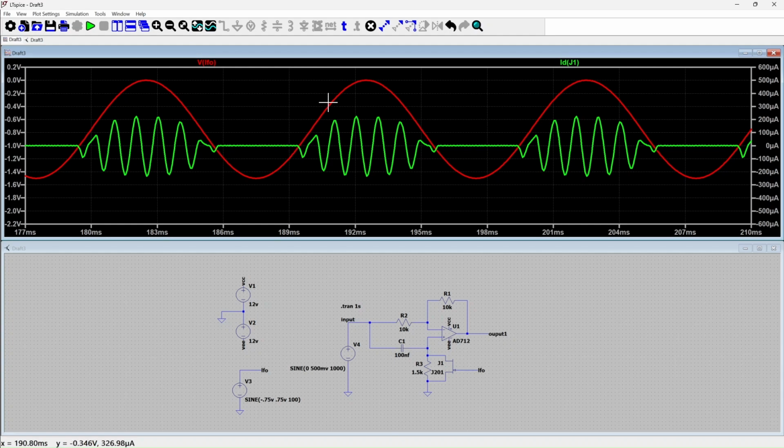Again, when the LFO voltage rises, the current through it starts to rise, and then once again it goes into a shutdown stage, effectively showing that this JFET is working as a variable resistor. So that's another way of looking at it.